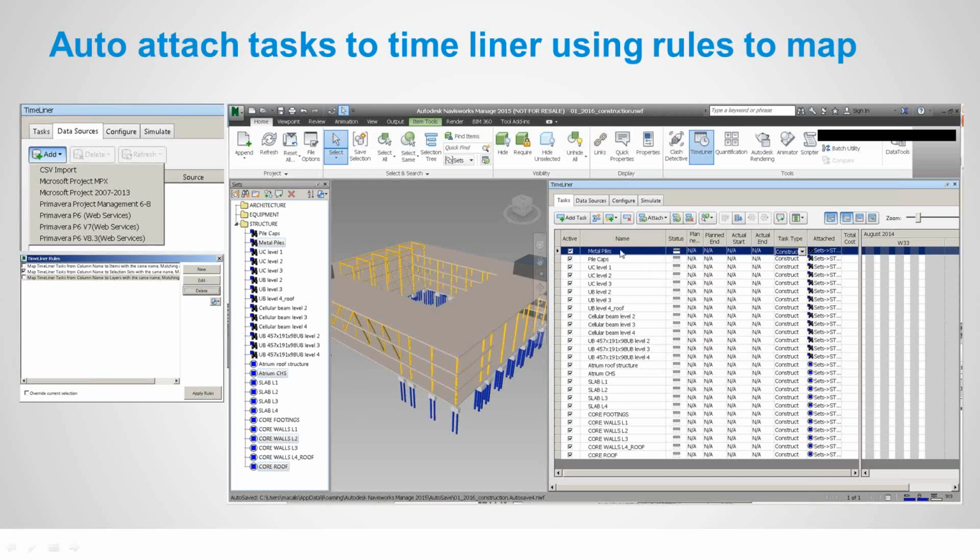You can put together your construction program to match the setup in the Navisworks Timeliner, and then you can go and you can automatically map that information directly to the geometry. So you can bring this information in from a spreadsheet, from a Gantt chart, or you can do it within Navisworks as well. The choice is yours, but it's a great way because there's a lot of automated tasks that will map the information automatically.